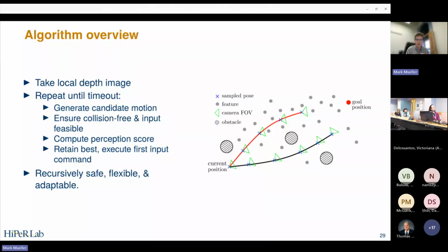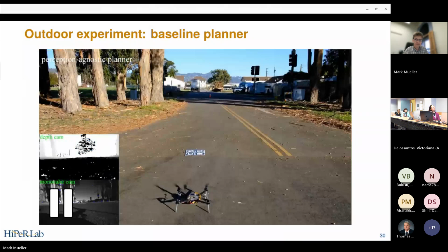So it's a sort of model predictive control receding horizon planner. And each of these candidates is designed to end at rest. So it terminates at standstill. So in the worst case, if I were to fly into an environment, let's say I fly into a tunnel and the tunnel is blocked, this is guaranteed to terminate safely. So this is guaranteed to come to rest in a safe condition. And of course, we might get stuck. The planner might get stuck at a certain point, in which case your higher level control will have to kick in with the global map of the world to get you unstuck.